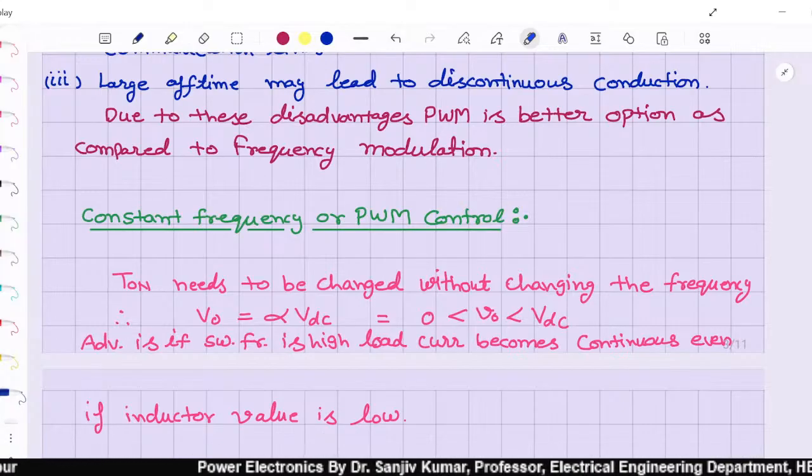And how we achieve it is very simple. You just use any op amp, just compare the DC reference voltage with a non-zero signal. It should be compared with a triangular pulse, right? Triangular or sawtooth or any. But for symmetry, let us say it is triangular, and the moment the value of the DC reference is more than the triangular, it will generate the pulse. Likewise, you can generate the variable duty cycle with the help of an op-amp, right?